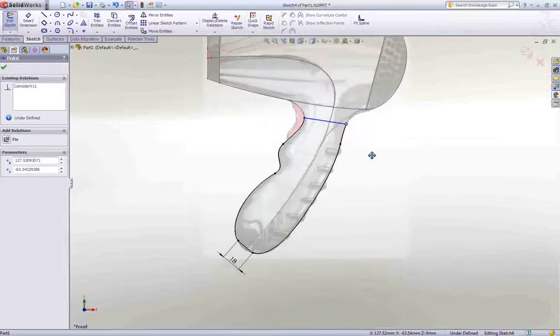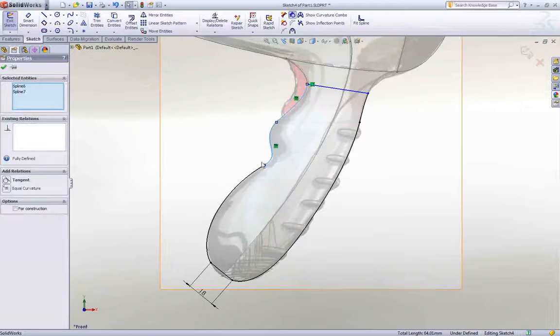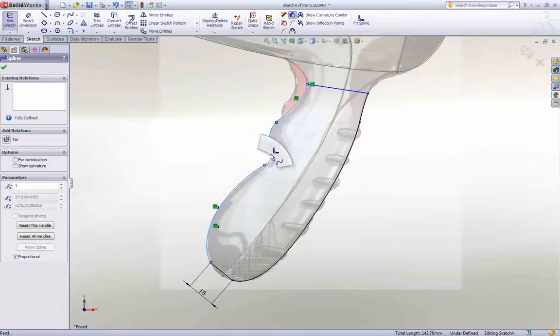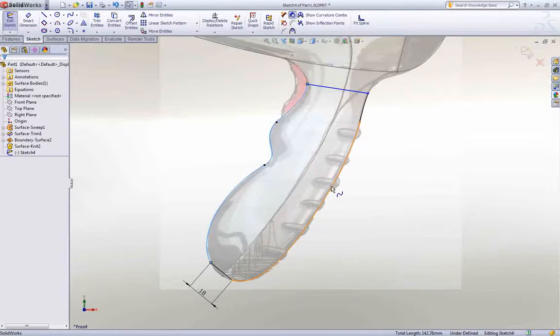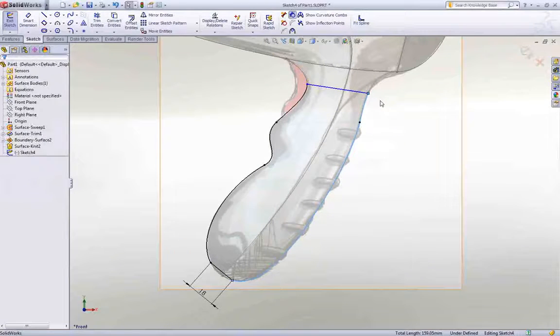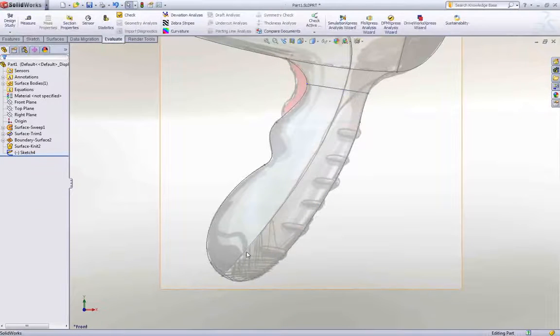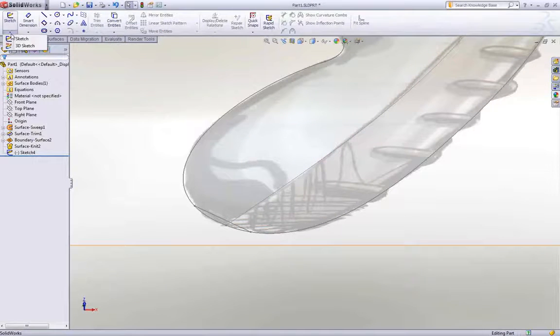One often overlooked issue is curve and surface parameterization. Curves of different length can cause unwanted kinks in a surface, and curves with multiple segments are even worse. One way to prevent this is to fit a spline through the curve to make it a single entity, but you need full control over the tolerance, which gives you control over the curvature. A simple composite curve simply won't do.